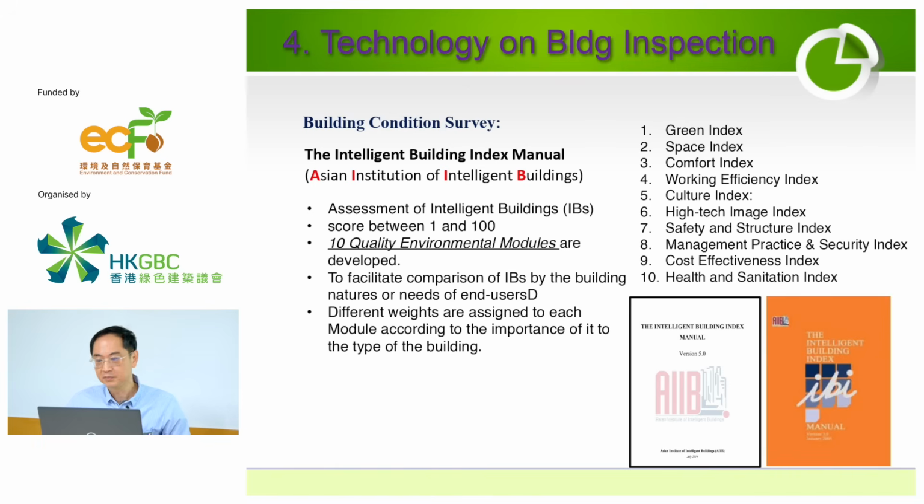Okay, before we stop for a while for the break, let's talk about a few slides about the building inspection, the building condition survey. Years ago, I helped the AIIB, Asian Institution of Intelligent Buildings, in writing their Intelligent Building Index manual on the chapter of the structural. The structural part is talking about how we assess the building inspection for crack, for water leakage, for spalling, using thermographic survey or condition survey.